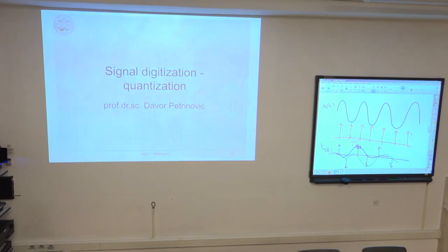Okay, is it still higher or lower? And you successfully go to the lowest possible, 1/256 for the 8-bit conversion, and you get the final balance between the weights and your oranges. So of course they need at least 8 successive steps to do the comparison if they want to have 8 bits of the output. It takes 8 clock periods to get the result.